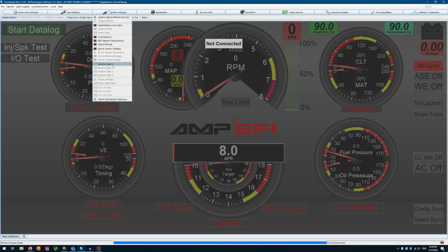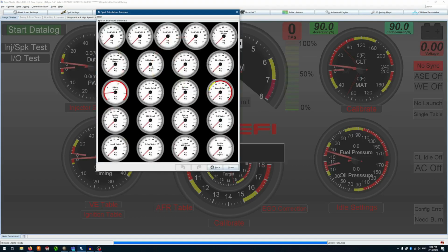Cylinder pressure is equivalent to horsepower most of the time. And the reason that we have lower horsepower than a stock CBR is because we're not letting in as much air. If we're not letting in as much air, then we don't reach as high cylinder pressures. And if we don't reach those high cylinder pressures, then we don't knock, and we don't need a knock sensor.